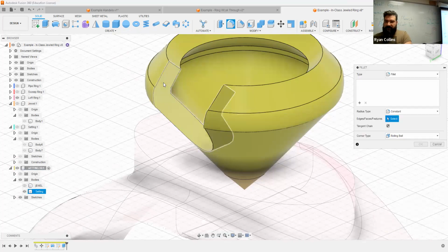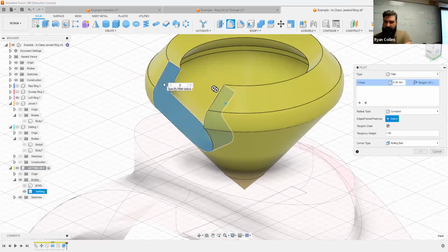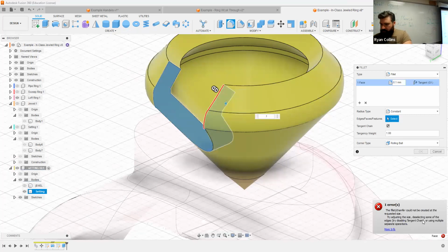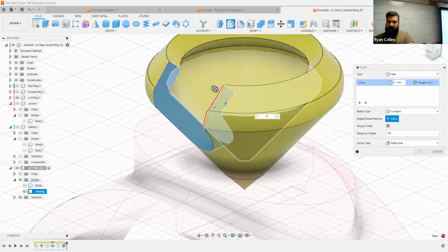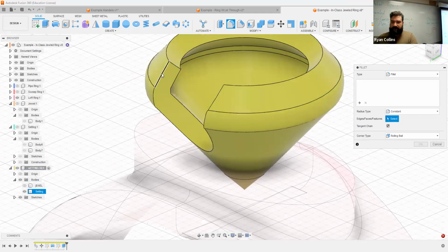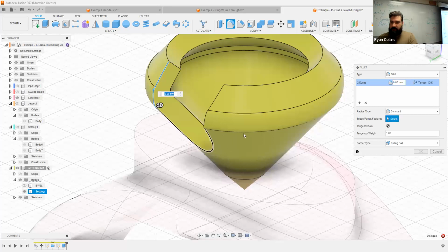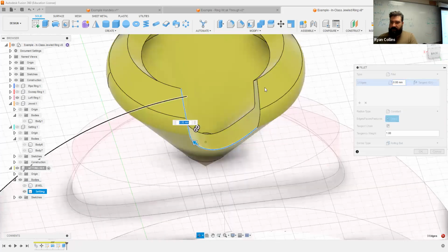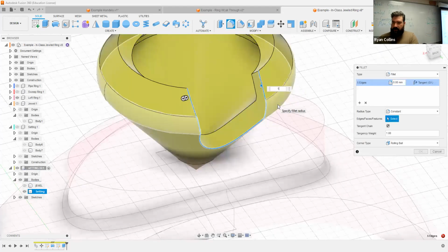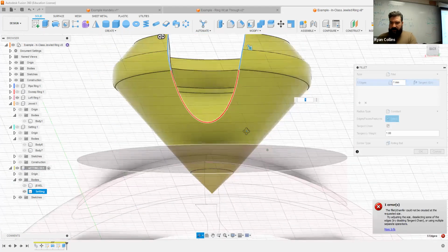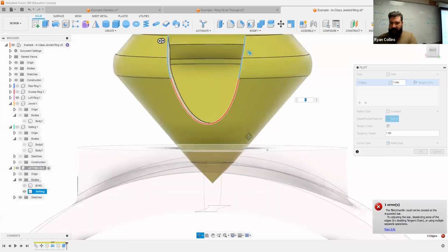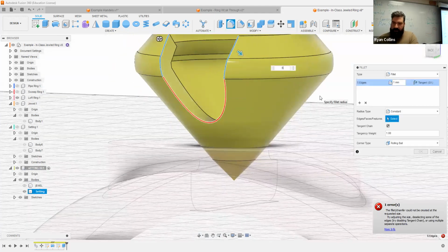That's fine. Let's use a fillet then. Let's try that. 0.5. Still too much. 0.1. Wow. That is surprising. All right. So maybe the faces is not letting me work. So let's try using edges. Just gonna do a rounded shape on the edge. See what that does. Really? Not letting me fillet that entirely. That is very strange. Well, I guess it's not. It's just a complex shape, and I'm trying to do weird things to it.